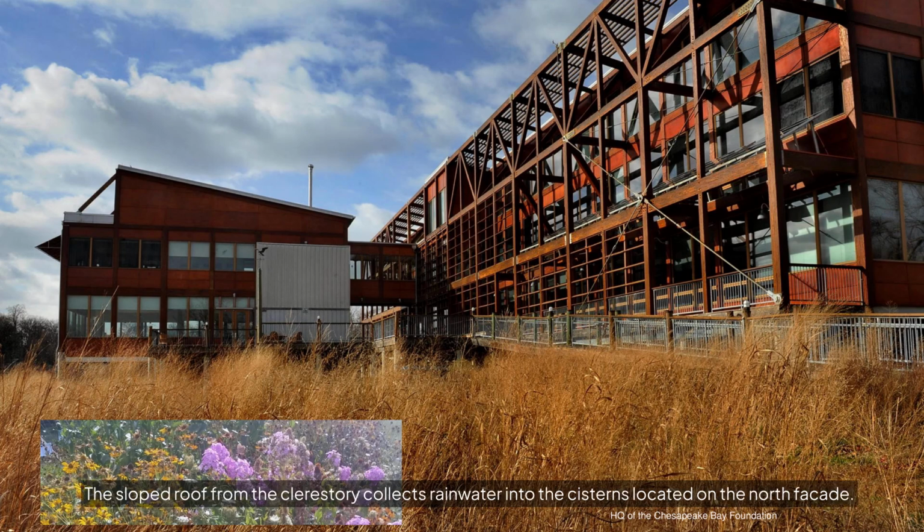The sloped roof from the clerestory collects rainwater into the cisterns located on the north facade. The overhangs provide semi-outdoor space and filter harsh sunlight before it penetrates the inside. The use of recycled and locally sourced materials contributes to carbon reduction. The landscape features native, flood-resistant plant species that require minimal irrigation instead of traditional high-maintenance vegetation. Bioclimatic design is accomplished through the consideration of site, climate, and building to create a sustainable, climate-responsive, and site-sensitive built environment.